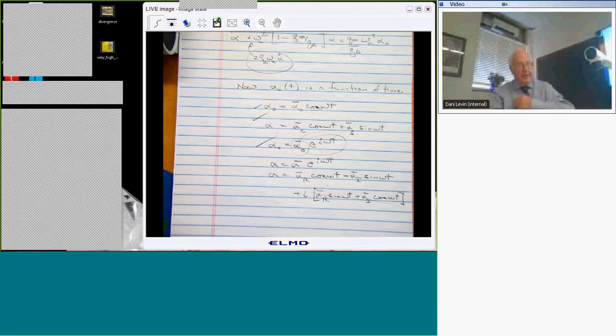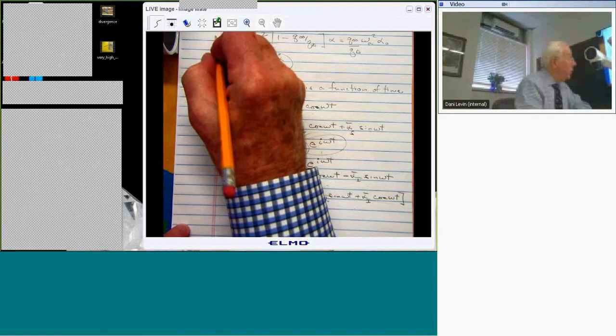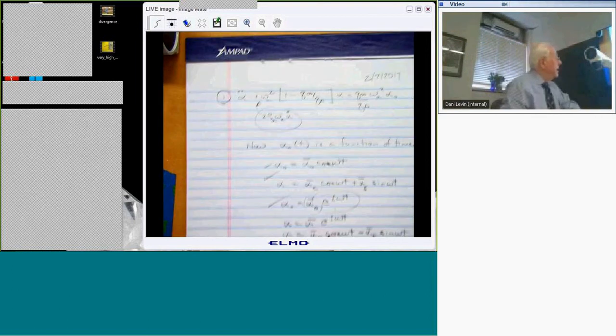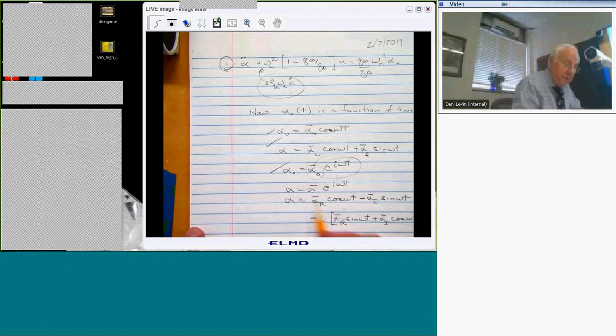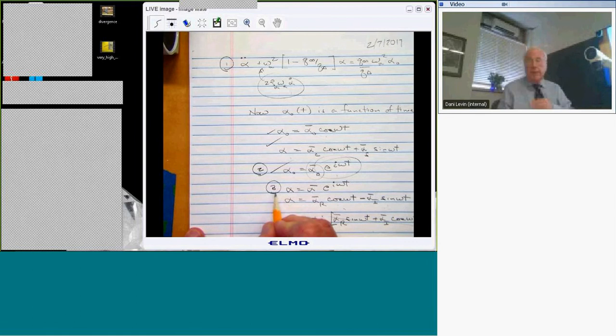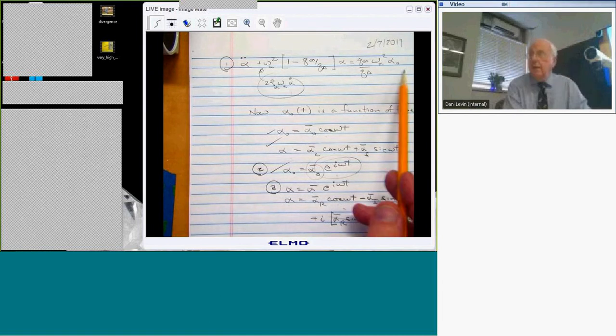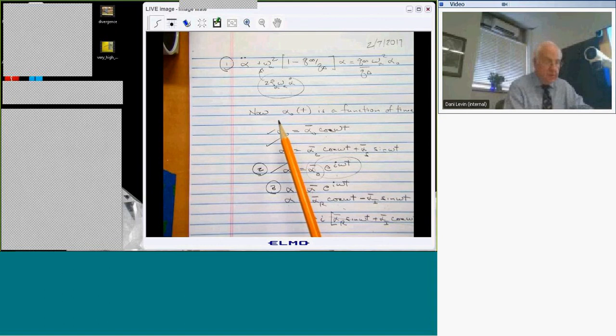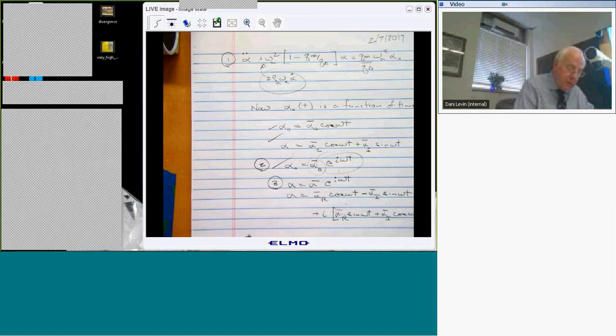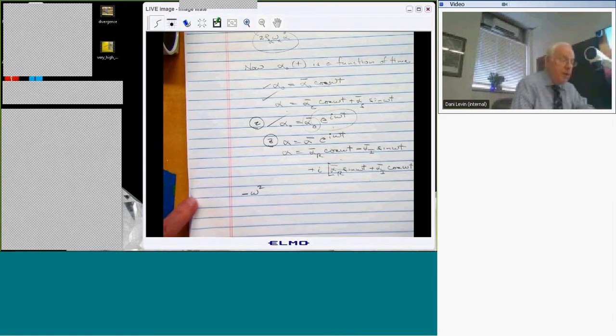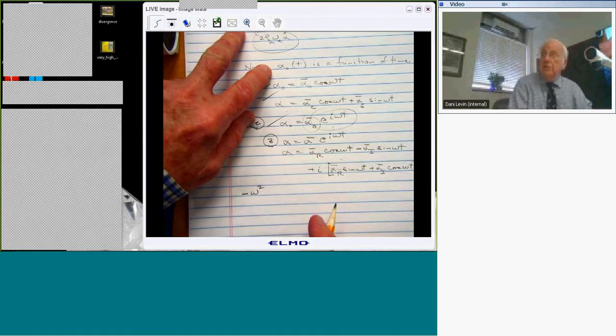Okay. All right. So I'm going to call this equation 1, and this will be 2, and this will be 3. And of course, I'm going to put 2 and 3 in 1 and see what I have. Since it's a linear system, everything's going to have an e to the i omega t, which will cancel out. And so I'm left with the following. I have minus omega squared, because it's alpha double dot. Each derivative in time generates an i omega, and it's i omega squared.